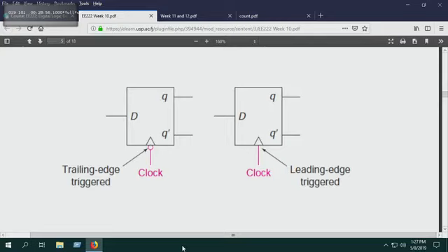Sometimes some of those videos you can translate on YouTube. You can translate other languages. So from those videos I picked up something. They were continually referring to the EGR. Then I researched the EGR. I found some forums, and on the forums it was, yes, that this particular valve, the EGR, is the exhaust gas recirculation valve, and that gets clogged up with carbon.